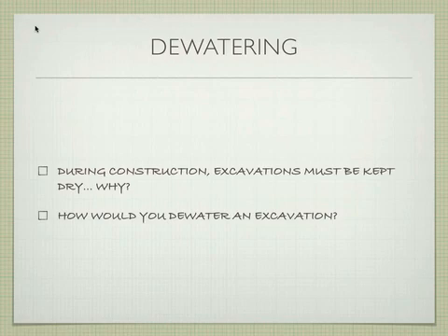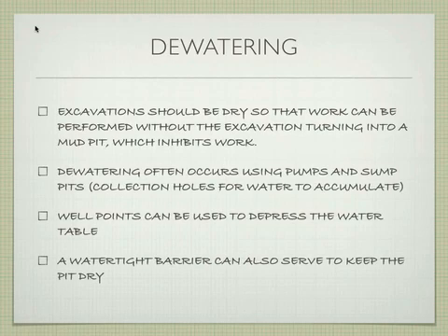Also, if you build a slurry wall, that becomes a waterproof barrier, which is helpful. Okay, so we'll talk about that. Okay, so excavations need to be kept dry so you can actually work, which should be relatively obvious to you. Okay, so dewatering often occurs using pumps and what are called sump pits.